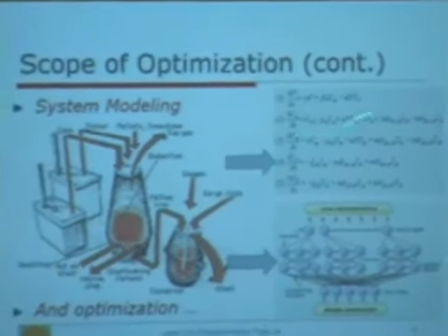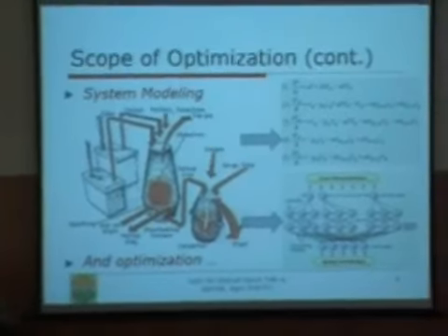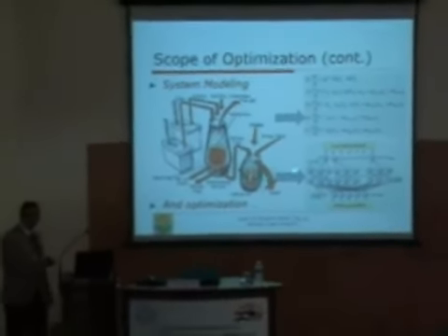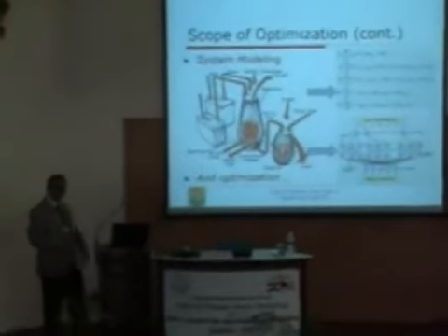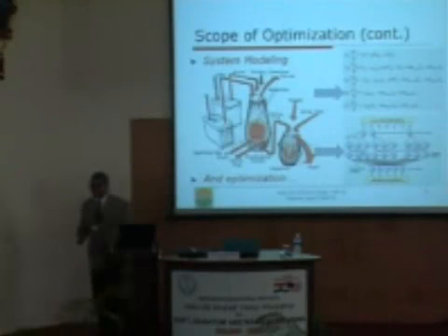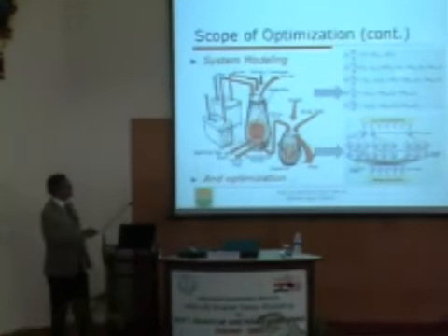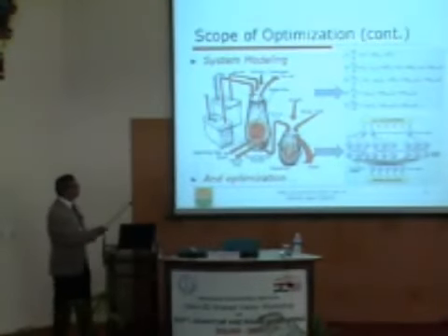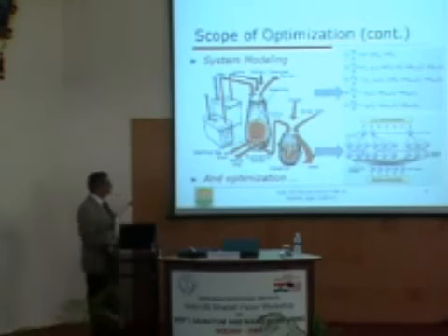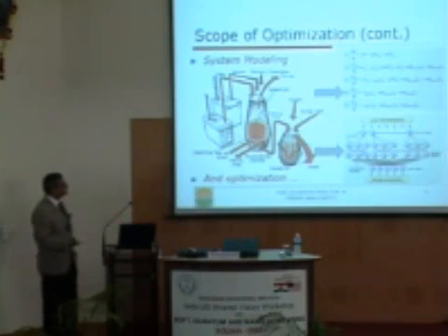So for a particular value of those, I run this model, and I check the output coming out of this model against the output of the plant, and the error that I have, I call that an objective function. So if I run an optimization on top, I may be able to get the parameters which are going to fit my data well with the model. So then you get an idea of the model. So that's one common way people do modeling.